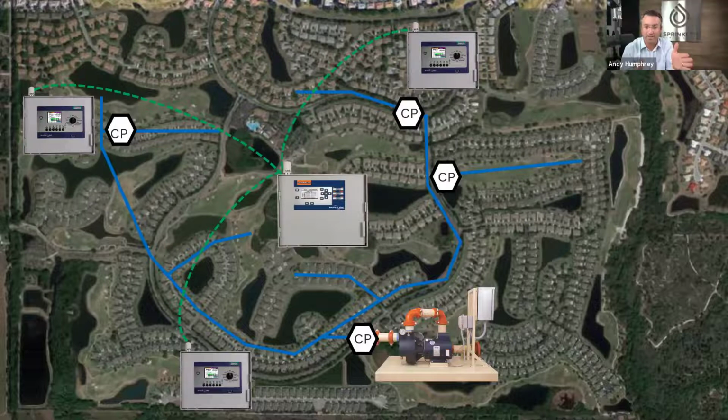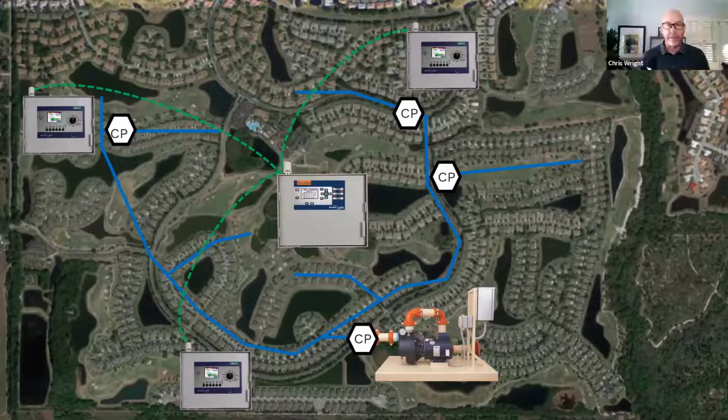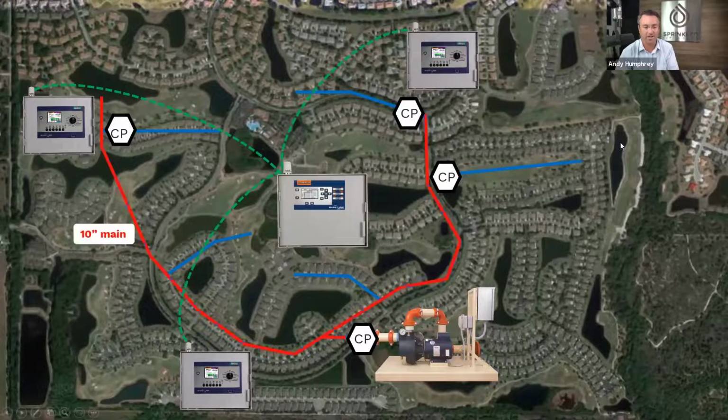Yep. And it's not a grouping that's side by side. That's why the words are sometimes confusing, because those devices could be a mile apart from each other. Correct. They have to open at the same time. Yep. And we all know that most sites actually are single controller, right? Most sites in the world, and many sites that are 150 zones might start with a 4-inch and have some 3-inch and have some 2-inch and have some manual isolation gate valves out there. And you can replace those mechanical manual valves with a control point and automate it.